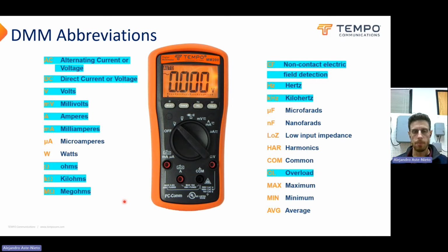However, you'll see it very often with resistance, because if you're taking a resistance measurement and you're not touching anything, there's a virtually infinite amount of resistance between these 2 points. With enough voltage, you can get an arc of electricity, but these multimeters are using very low amounts of voltage to test for resistance. So this is going to result in an OL reading on your multimeter.